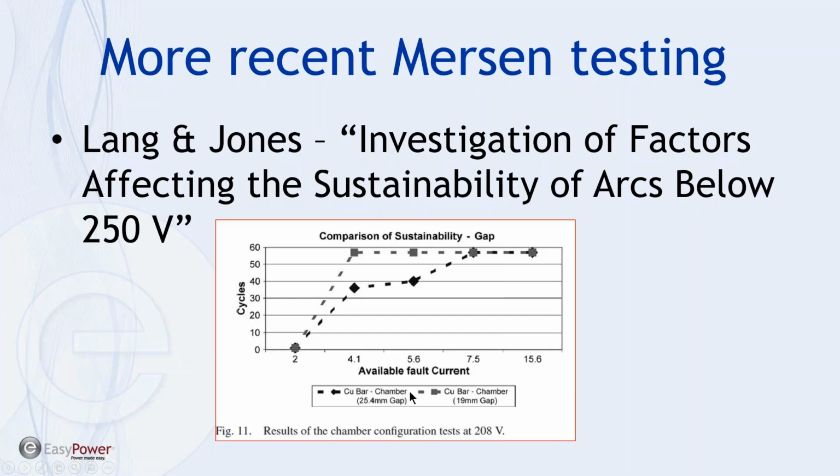Now, I think it's safe to say that the wording, the verbiage in the current 1584 standard takes this into account, and that's what allows us the 2-second limitation across the board if we need to at 240 volts.